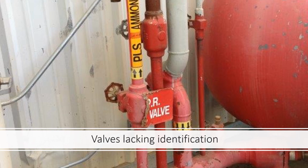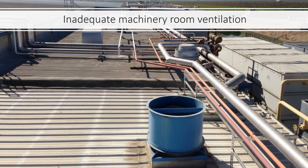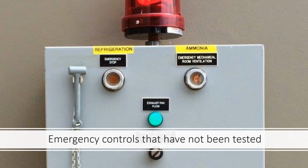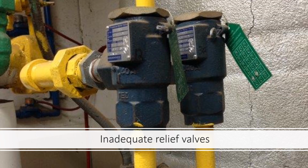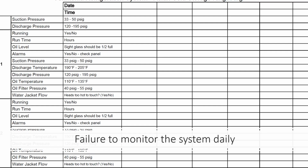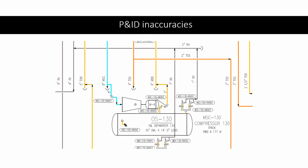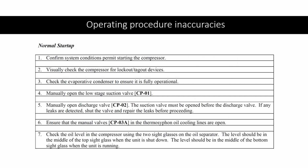important valves such as king valves lacking identification, gas detectors that are not functional or have not been calibrated per manufacturer's recommendations, ventilation systems with inadequate airflow or systems that have not been interlocked with detection, emergency controls that have not been tested, relief valves that are undersized, the incorrect set pressure, or haven't been replaced within the last 5 years, eyewash and safety showers that are not installed, don't have adequate water flow, or aren't located in close enough proximity to the system, failure to monitor the system daily, facilities that have not obtained important technical documentation such as manufacturer data reports, P&IDs that contain inaccuracies, and SOPs that do not reflect the actual practice of the facility operators.